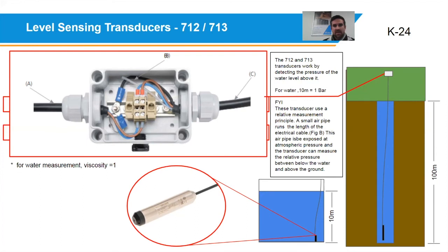There's no absolute setting and there's no drift. If the pressure changes, or anything changes, the sensor can detect and compensate as well. So that's this tiny little 1 or 2 millimeter pipe that's exposed to atmosphere. If you blow or suck on that pipe, you would physically see the level or the signal change as you're changing the reference point of that transmitter.